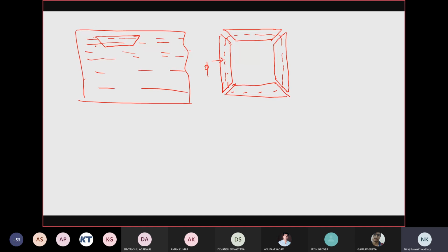It has been observed that the least magnetizing current Im is obtained when the magnetic material is cut at an angle of 43 degrees and 47 degrees. Suppose this piece is cut here at 47 degrees; if this angle is 47 degrees, then the objective is that the other adjoining one should be 43 degrees. Okay, so for this angle of cut it has been observed that the least magnetizing current will be required. So this is all about the construction of transformer cores.